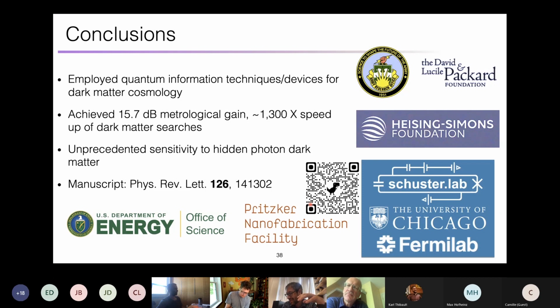Yeah, so there's that cavity, and then everything is covered in copper, both to seal it but also to thermalize it. So the microwave photons can't get out or in, but if we didn't do that, IR photons could potentially get in. I guess it probably doesn't do very much against radiation, but maybe some sorts. And then we put it in magnetic shields, and then again in several layers of radiation shield as well. Okay, that's good.